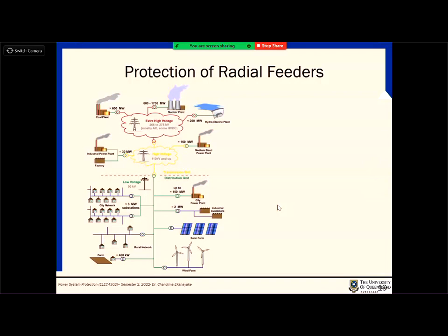Okay. Now what we are going to look at is how we are going to use these sort of relays with these given relay characteristics, IDMTs, on a radial feeder. When you're looking at this sort of feeder, say I have a relay here or circuit breaker 1, and relay 1 is driving that circuit breaker. So if you put a relay at that point, then of course the whole feeder is protected, right?